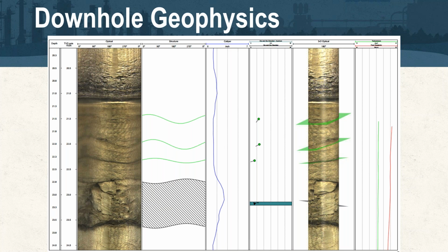There's a number of questions here about the tooling itself. Some of you have asked about the biggest differences between ATV and OTV. Briefly, ATV is an ultrasonic acoustic image that's inferred, and the OTV is a physical image. It uses a CCD sensor, just like what's in your DSLR cameras. So that's a true actual photo downhole of the borehole. There are some other questions here about calipers and HPFM. So we'll reach out individually because that's a lot to digest here.